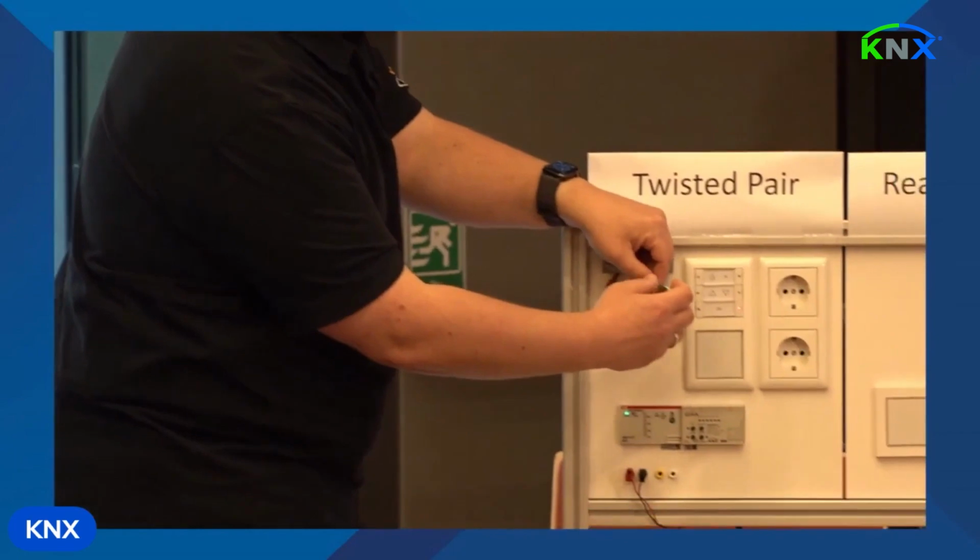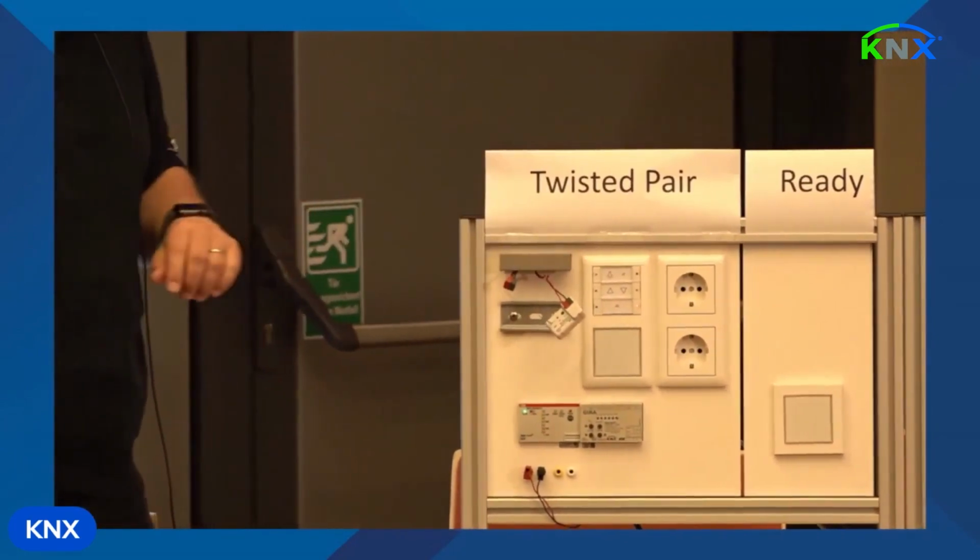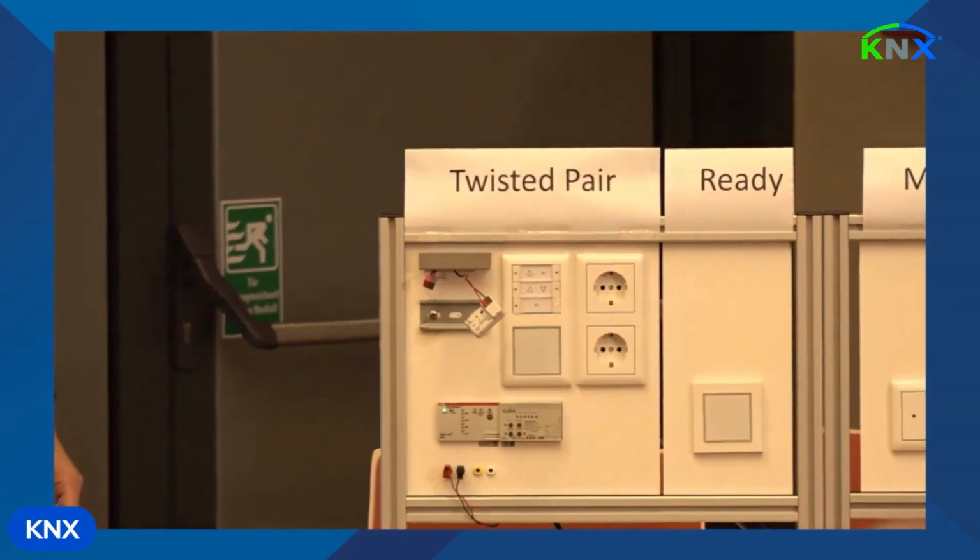Wherever you add a media coupler or RF coupler into a twisted pair line, ETS today, with the old version, says this doesn't make sense. It's a twisted pair line. The new version says, okay, obviously you want to have a segment of this line being radio frequency. It creates the radio frequency segment and adds the media coupler into this segment automatically. And also it needs to be physically connected. So I added here, got power, okay. Okay, so now I have this segment.